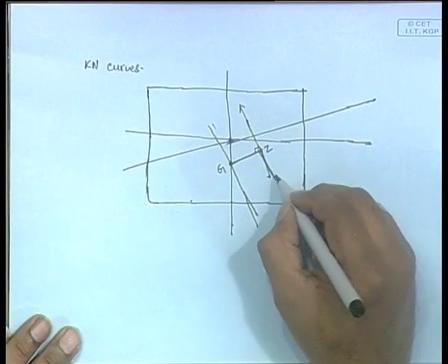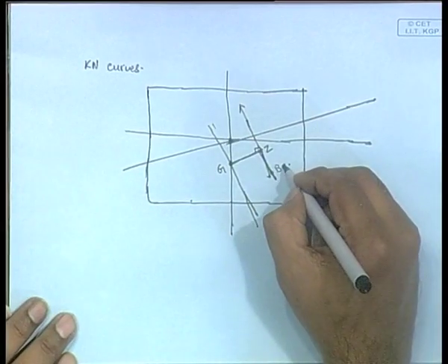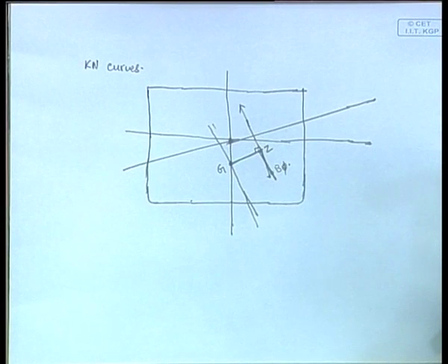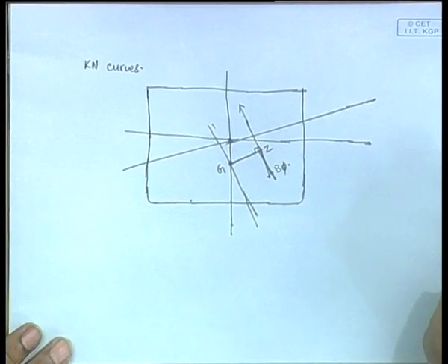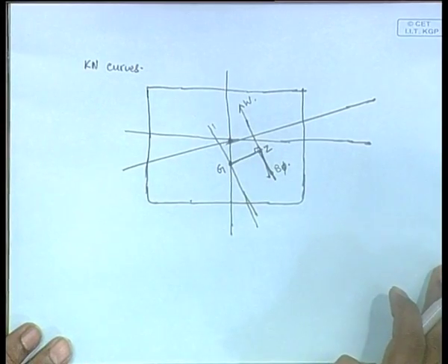So, this is the righting arm. Here somewhere you have B theta, or B phi. Initially you had the ship in an upright condition, something caused it to heel, and as a result it has moved into the new position B phi, and we have drawn the vertical there, and GZ is the righting arm. So, the weight W is acting here upwards.